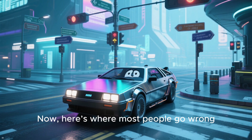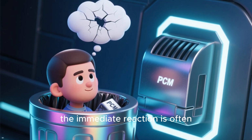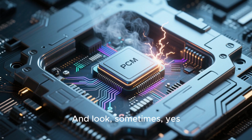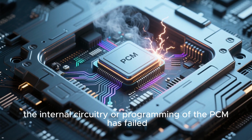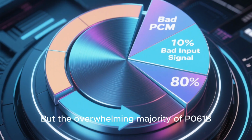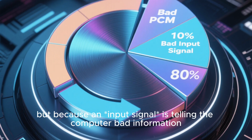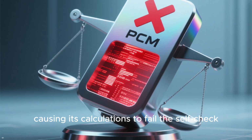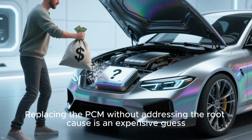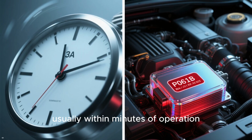Now, here's where most people go wrong. Because P061B is labeled as an internal control module code, the immediate reaction is often, the PCM is bad. Replace the computer. And look, sometimes, yes, the internal circuitry or programming of the PCM has failed, requiring replacement, but the overwhelming majority of P061B codes are set, not because the computer itself broke, but because an input signal is telling the computer bad information, causing its calculations to fail. Replacing the PCM without addressing the root cause is an expensive guess. And trust me, the new PCM will set the exact same code, usually within minutes of operation.